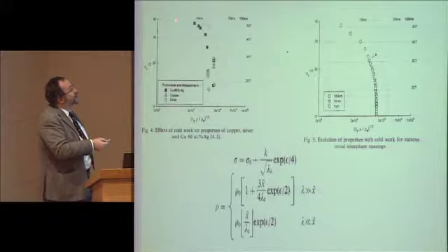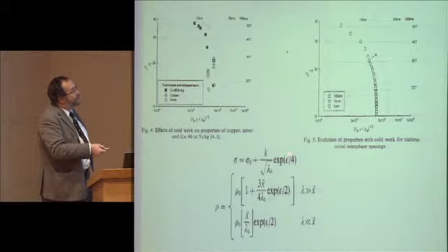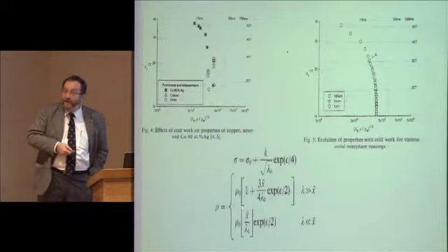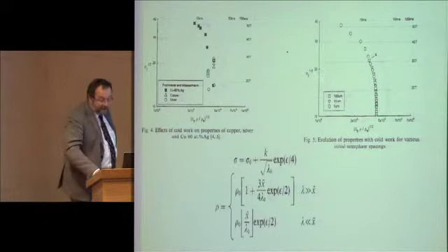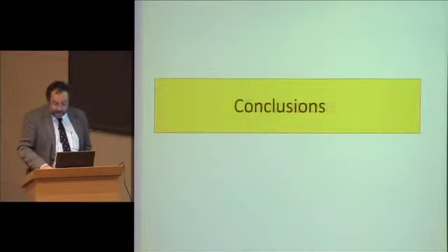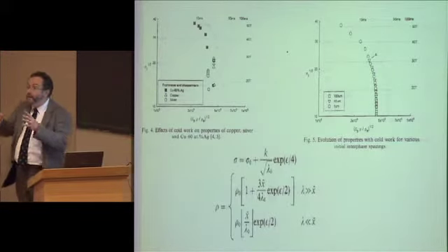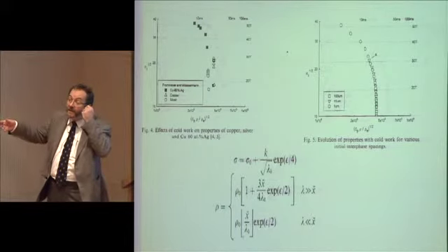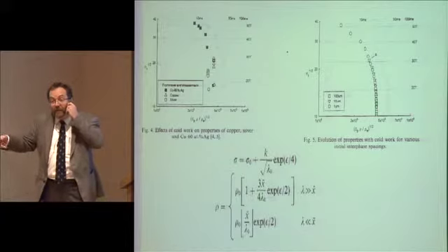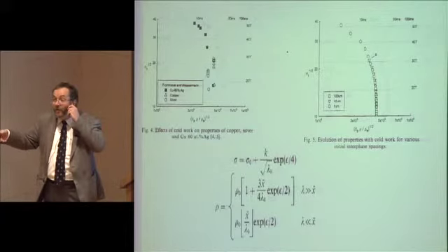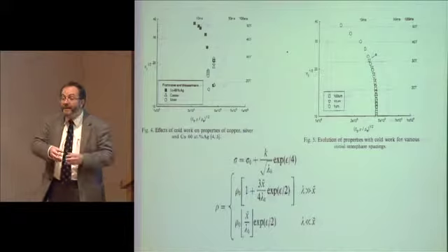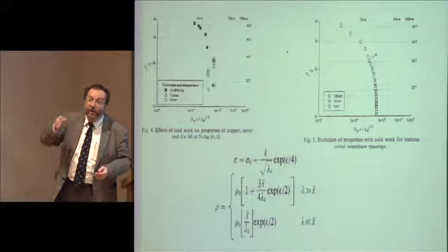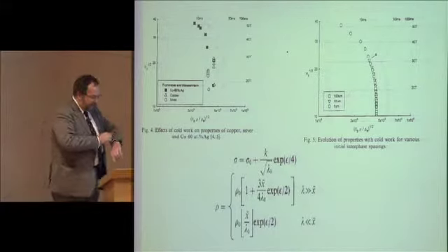What the modelling says here, on more or less deformed copper-silver, is easy to understand. It's a very simple model. You can say that you can't do both things at the same time. You need to optimize. So for this particular criteria, copper-silver or copper-niobium are good, and you need to have such or such an initial spacing. You need to deform it with such or such an extrusion process to obtain a material that is the best fit for a long pulse magnet or a high field magnet.